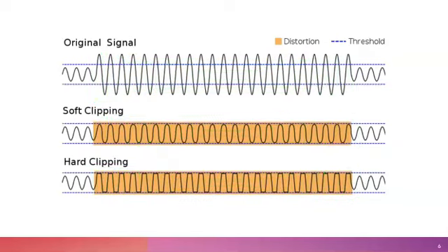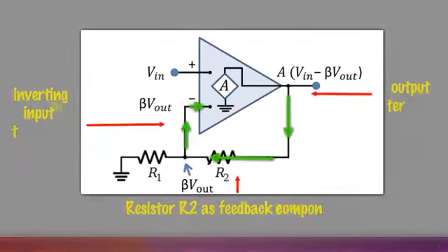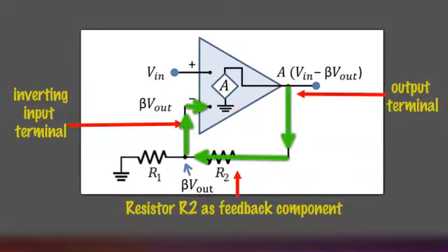Therefore, by using a negative feedback within the electronic circuit design, the huge levels of gain can be used to good effect, providing flat frequency responses, low distortion, and very defined levels of gain for the overall circuit, not dependent upon the actual gain of the IC, but on that of the external components whose value can be accurately chosen.